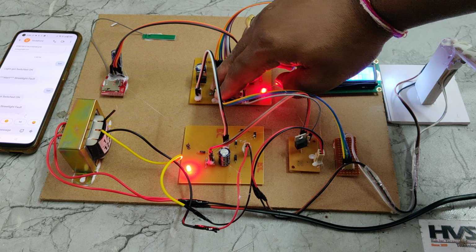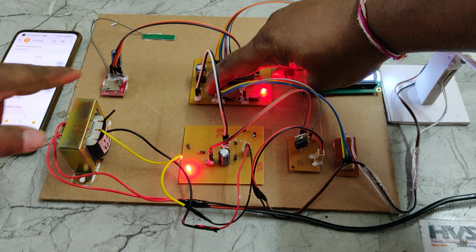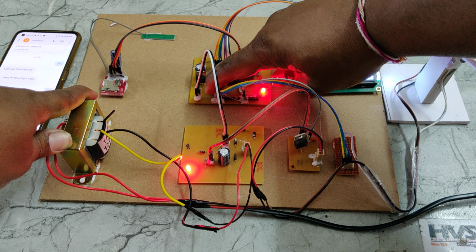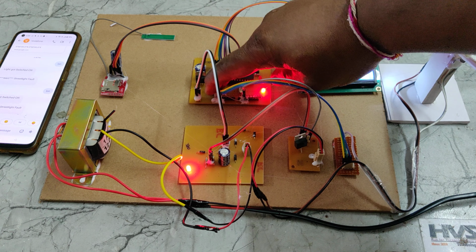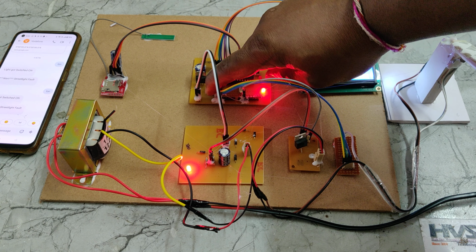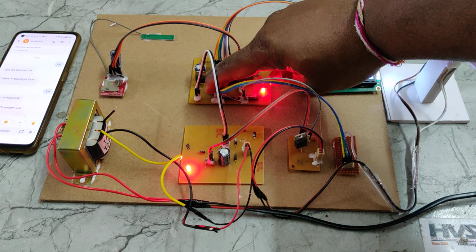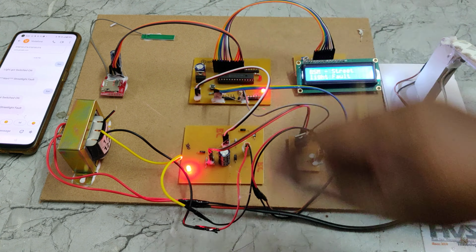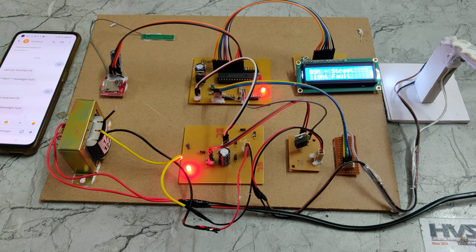So this is the reset switch. Hold this reset switch till the GSM modem blinking rate slows down to 3 seconds. Now it's blinking at 1 second duration, which means it's trying to get the signal. Once the GSM modem gets the signal, you can see that the blinking rate slows down. Now you can release the switch. Okay, release the switch. A welcome message is displayed on the LCD screen.